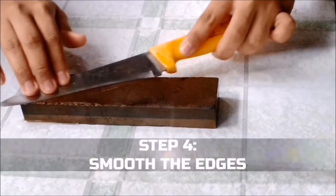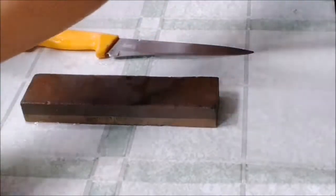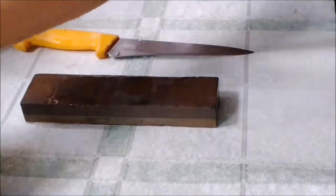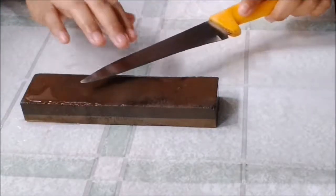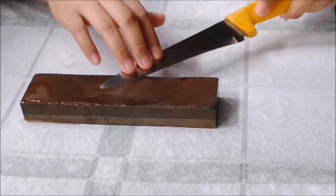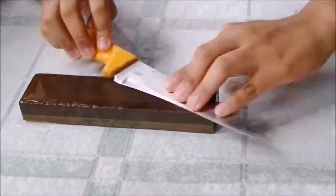Step 4. Smooth the edges. Once you've achieved the proper angle and sharpness, move to using a finer grain whetstone and continue sharpening until you achieve a razor sharp edge. Don't reduce the bevel edge to less than 1 mm thickness.